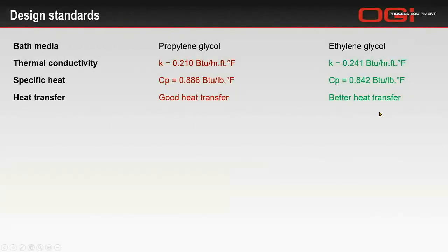The only thing better than ethylene at heat transfer would be water. However, most people will not use water in water bath heaters, and the specific reason for that is you may get freezing issues, which is why glycol is used. Glycol also elevates your boiling point, and it has rust inhibitors and corrosion protection built in to protect all that carbon steel inside your shell.